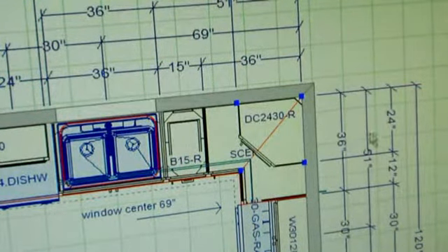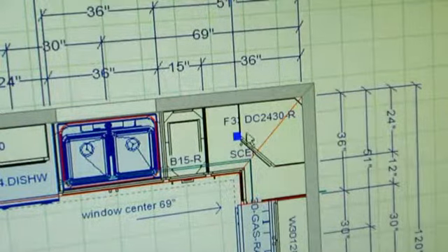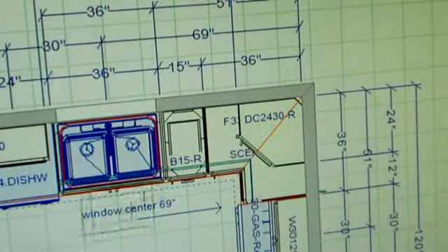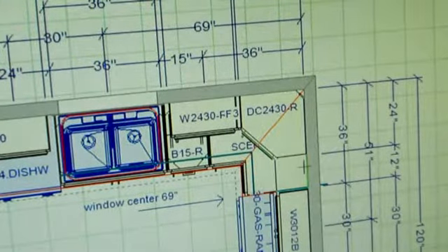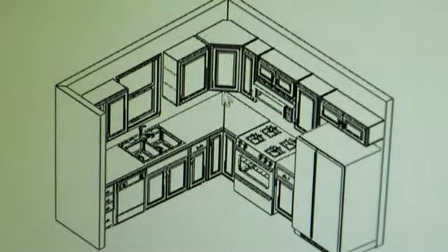So now we're going to do the diagonal corner, which occupies 24 by 24 inches of space. And remember, I pulled that blind corner 1 inch. So there's my little 1-inch filler because I pulled the 1 inch, which is 49 inches. So I know automatically I need that amount of space. And that's where I would want to put a spacer, between 2 cabinets. Then on the right, we want to occupy 36 inches of space. So since the diagonal is 24 inches, I can plug in a 12-inch wall cabinet and we have 36 inches. So let's go ahead and take a look at this. It looks nice, but there's some odd sized doors in there. Things aren't quite as symmetrical as what we were hoping for.